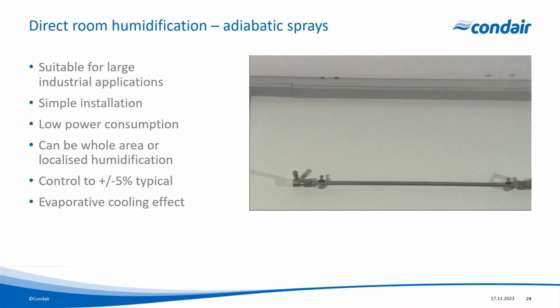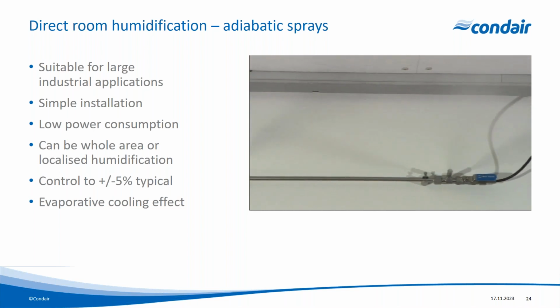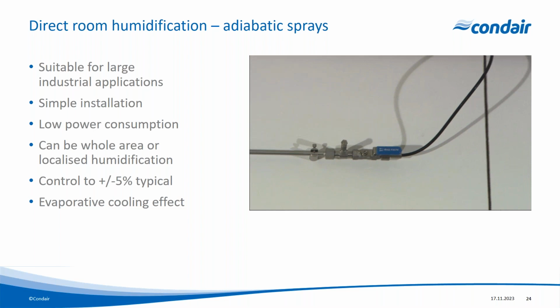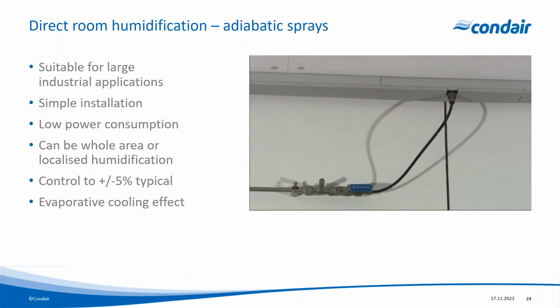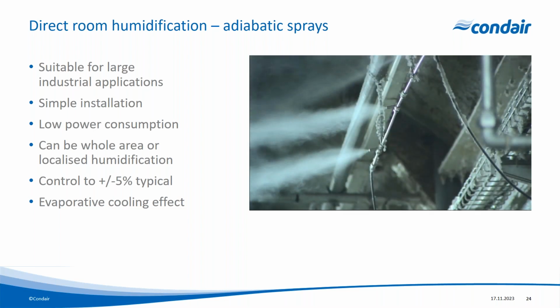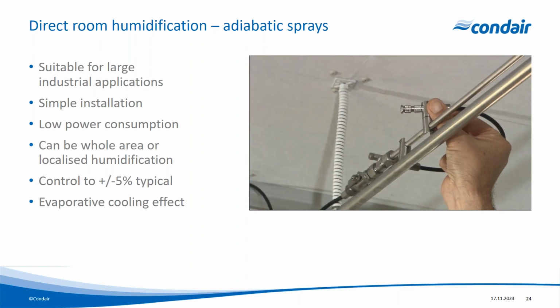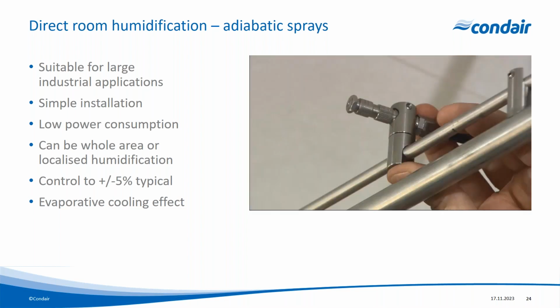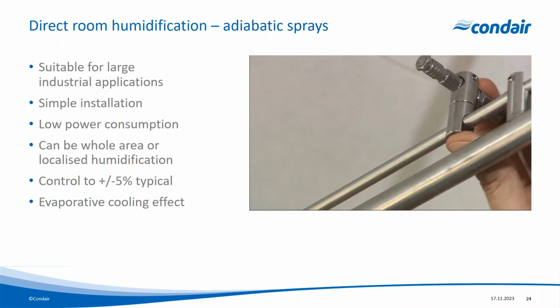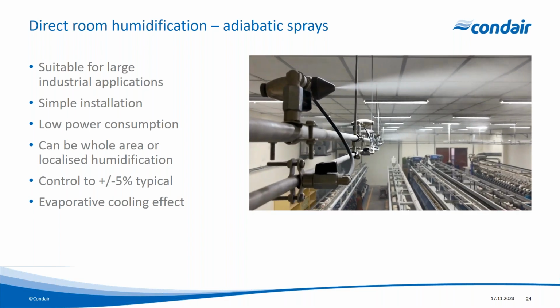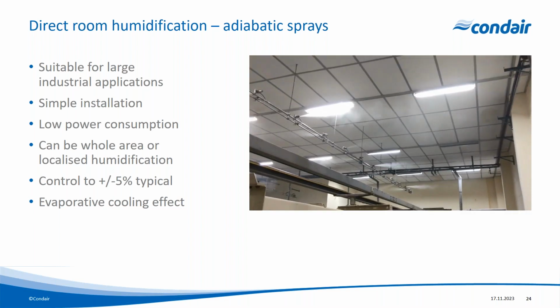There are different applications as well where we don't want fan assist, where we can just use a system to spray straight into a space. And that may be somewhere where we don't want any electrical motors, so perhaps an ATEX rated area, where we can just spray and then dissipate. And we typically pulse the spray in. We spray a certain amount, then let it distribute, and then spray again.